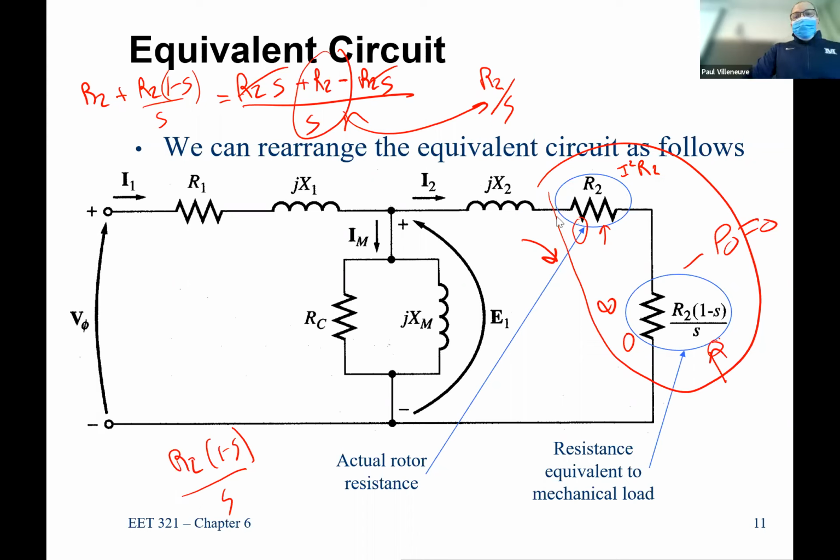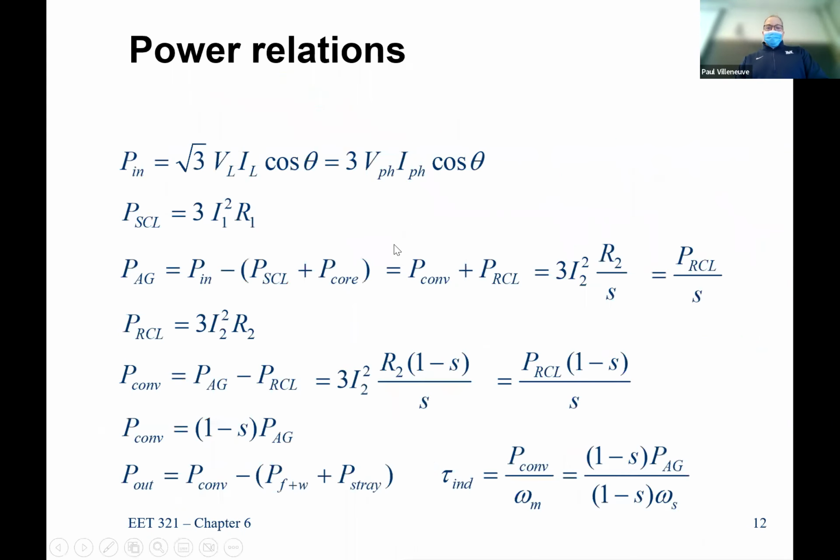You can't do too much with R2. You're kind of limited. I mean, you can do more stuff, but then you actually have a bigger shaft. It gets to be some problems. So the thing you do is run at higher speeds. Remember, I promised I would explain why they run so darn close to synchronous speed and not at half speed, because you would get a really hot motor. And that's where all the losses are in a real world motor, I squared R.